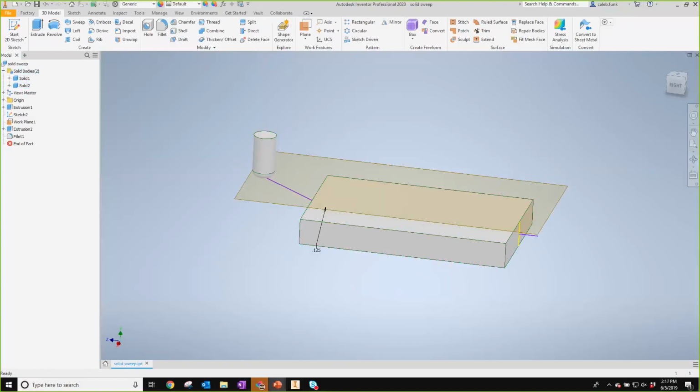So you don't want overlapping segments, obviously, in a tool path as you put it in. The main tool body should be at the start of the path, and the path has to be tangent. At least G1, that's tangent, or it could be G2 smooth, but it has to be continuous. Typically, our best results are going to be with G2. So this little tool body that I have, I'm keeping it real simple. And typically that's what we want. If you're trying to sweep this really complex thing along there, it is going to be pretty difficult when you're going through and doing that.